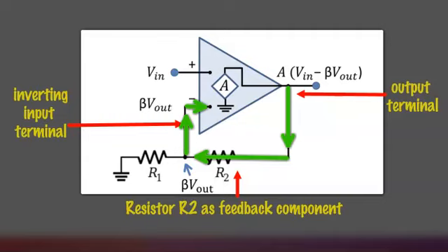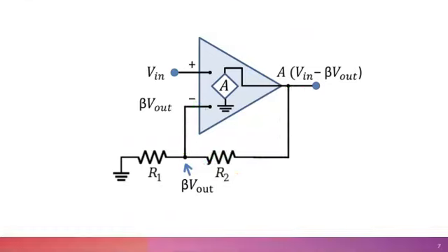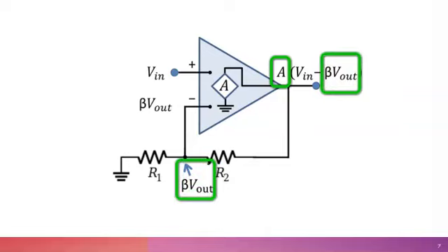The other condition for op-amp is the closed-loop gain. This form of gain is measured when the feedback loop is used, creating a closed loop to the circuit. By applying negative feedback, the overall gain of the circuit is much reduced and can be accurately tailored to the required level or to produce the required outputs, as in the case of filters, integrators, and so on.